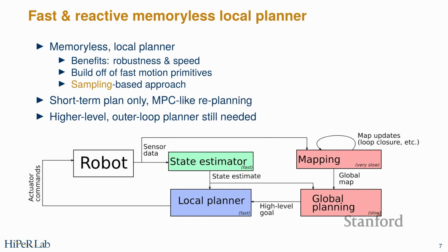So one of the things that we've been interested in and working on for a few years in my group is to try to put more intelligence in the lowest level control. And specifically, how can we do really fast reactive planning inside this innermost layer? The idea is now you move a lot of the safety critical aspects from the slow outer loop into this inner loop, and that potentially isolates you from problems in the outer loop, makes you more robust, and gives you hopefully better overall performance as well. And really the idea here is I have rich sensors, I have more compute, so I can put more high frequency computation to do feedback control and planning at this innermost layer, and how can we go about doing this?